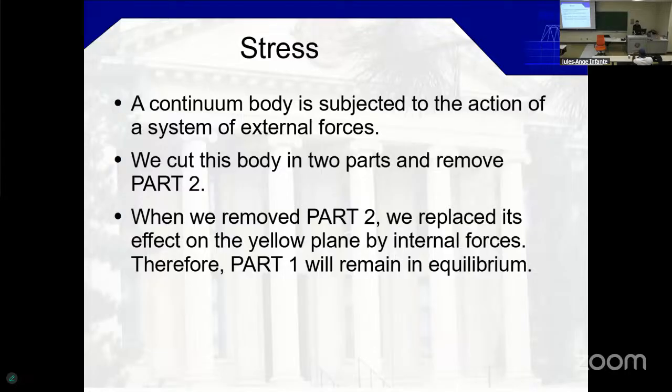Now, unlike pressure, pressure is omnidirectional, so it's a scalar field to begin with, right? But stress itself is directional, okay? And you will have different components of stress. You have normal stress, you have shear stress. So you need to define the state of stress of an object.